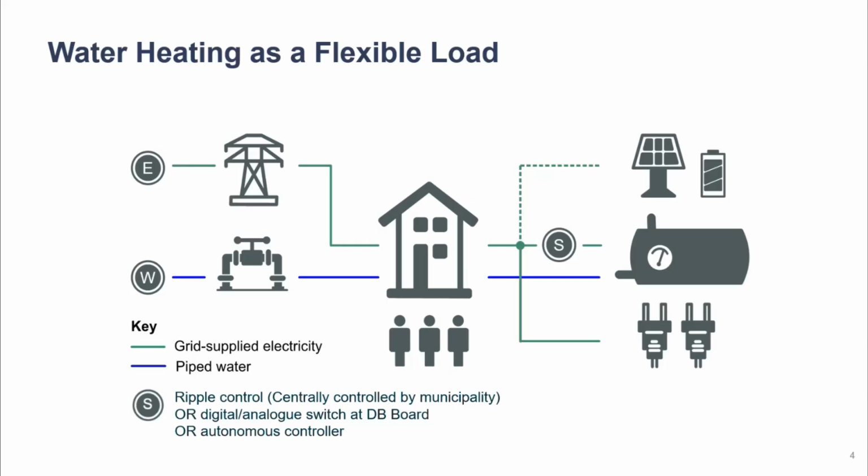The other thing I wanted to mention here, although this is not a standard household, is that you could also use an external switch, and that's where that flexible loading really can come in. So typically the water heater is controlled by a bimetallic switch, so it really looks at the temperature of the thermostat, but you could also produce an external switch to define when you allow that element to turn on. So it's 2 switching motions over here.